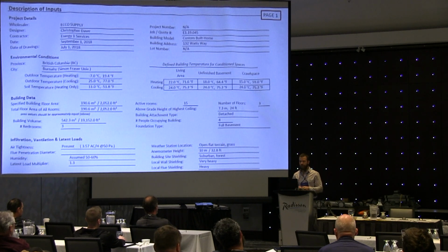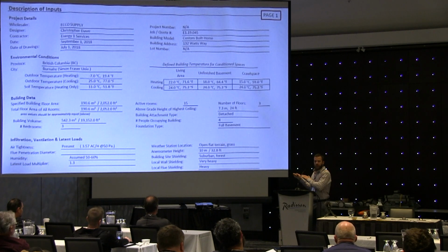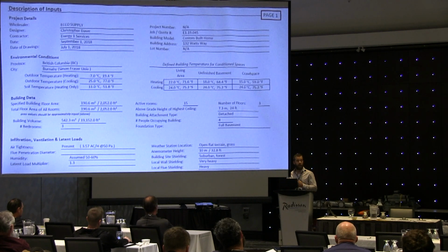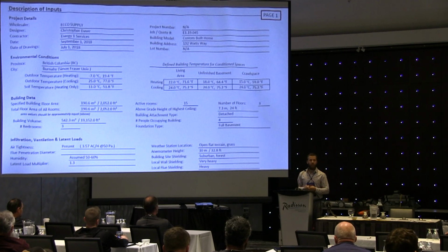And so the only thing we need to do here is there needs to be communication, right? If I do my entire heat loss to say this house is very, very, very airtight, whoever's building the house needs to know that, right? Otherwise, if they just build and away we go, we need to make sure that this is actually met, or our values won't be accurate. So what might happen is I might know that the builder I work with builds to 2 air changes per hour.